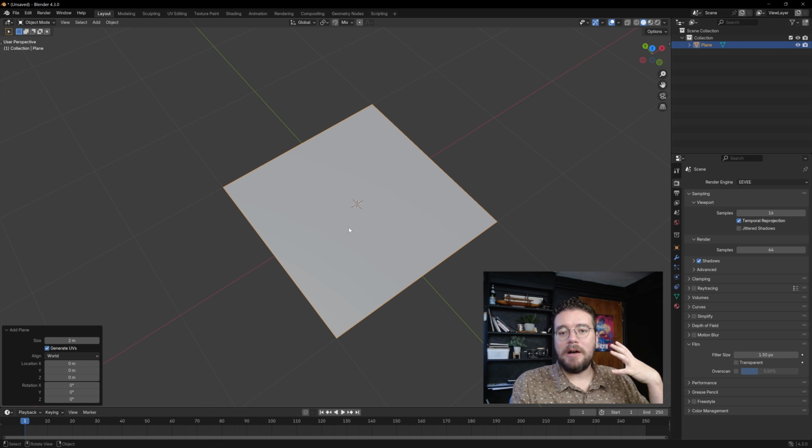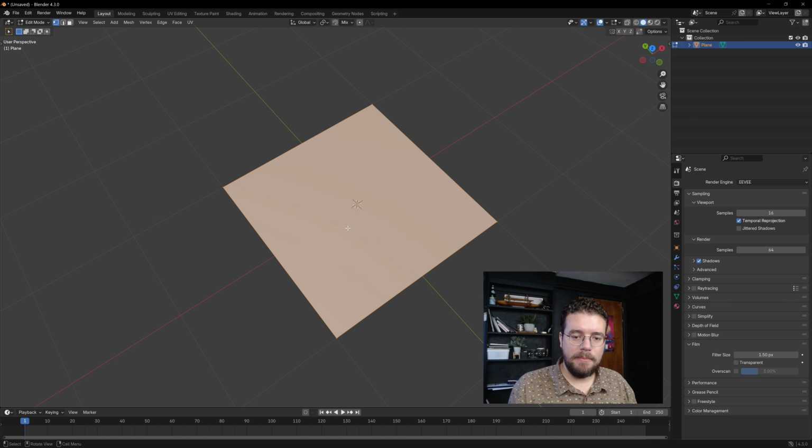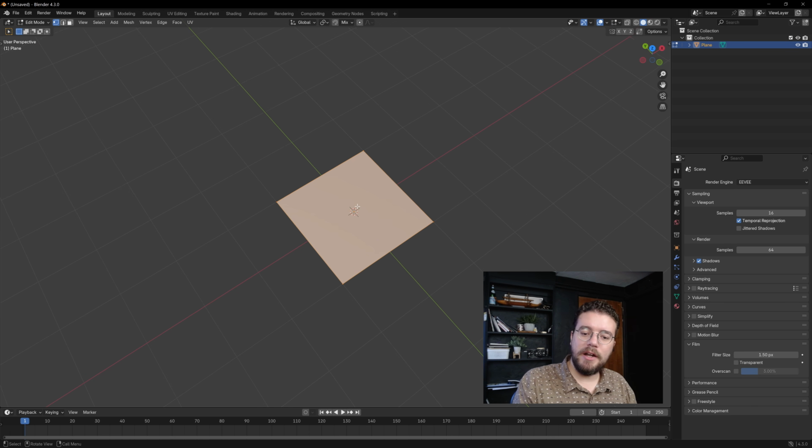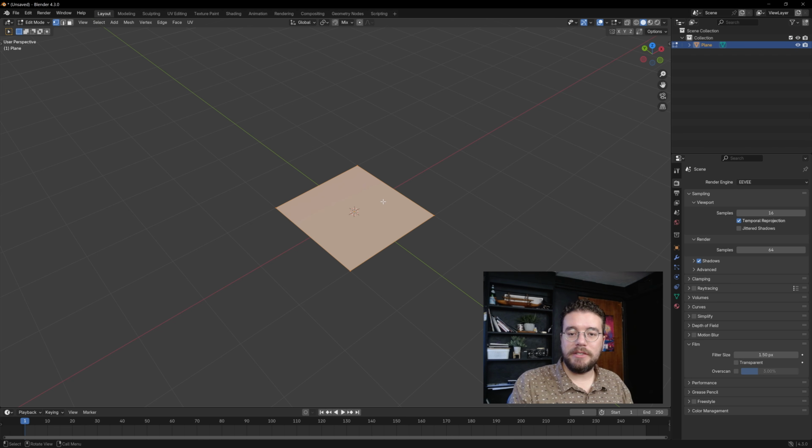And now let's just talk about one more edit mode function. So let's go to edit mode. And I want to show you how to add what's called a loop cut. So a loop cut is, remember the loop that we had around our cube earlier? We can add more loops to an object with Control R.